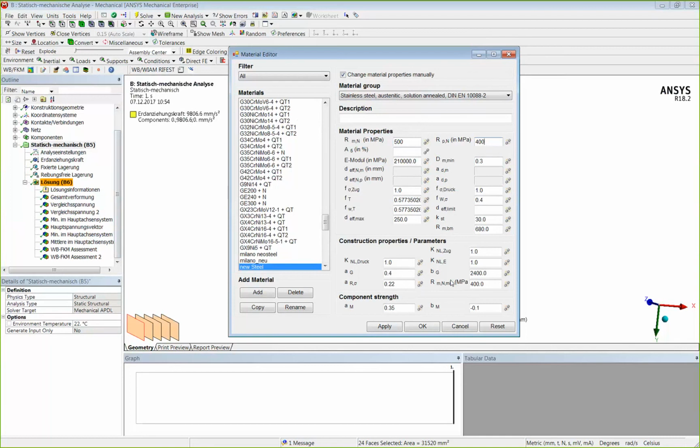Good. You will receive a copy of this presentation. And what is in the FKM inside ANSYS is all three modules we have seen here: welded, unwelded for solids, welded with shell elements for a nominal stress approach, welded for shell elements with structural stress approach.